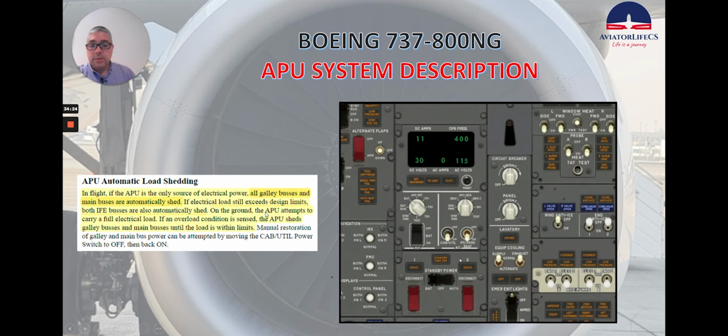On the ground, the APU attempts to carry a full electrical load. If an overload condition is sensed, the APU sheds galley buses and main buses until the load is within limits. Manual restoration of galley and main bus power can be attempted by moving the cabin utility power switch to off, then back on.